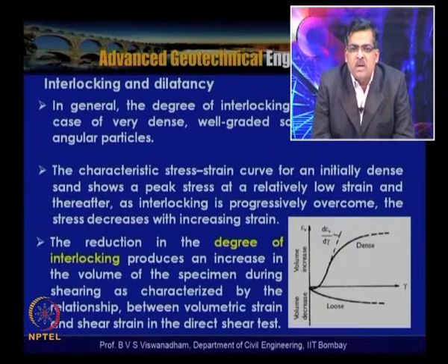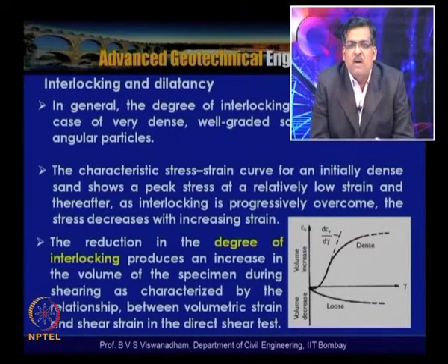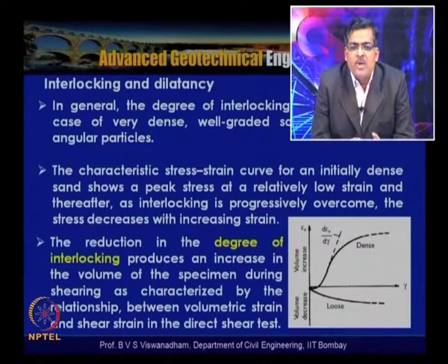This reduction or breaking of the interlocking results in an increase in the volume of the soil specimen which is being subjected to shear, as characterized by the relationship between the volumetric strain and the shear strain in the direct shear test.